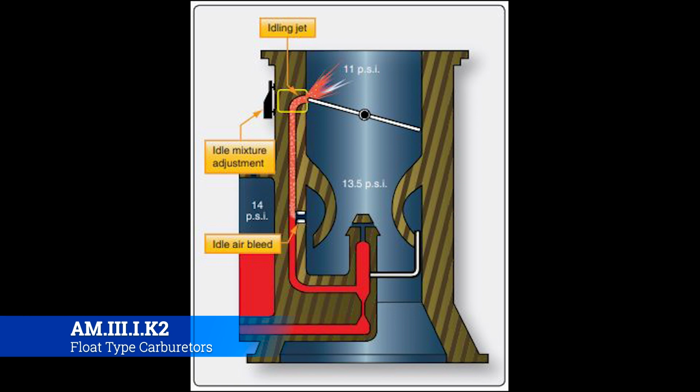But also, you'll see it whenever fuel evaporates, they'll leave that additive behind. Well, if this happens multiple times over a period of years, you could easily get into a situation where that gunk is just starting to collect around that idle jet, and you'll start to see it attract dust and dirt and anything else that might be in the air that's coming through there. Also, if you do a lot of off-airport landings, this is a thing that could get gunked up just from operating in the environment that it's in. So that is the idle system.